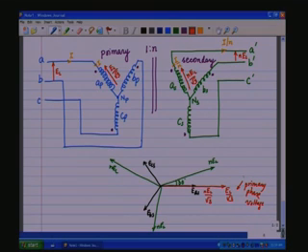And the line voltage is going to lead the phase voltage by 30 degrees. So, therefore, you will have the line voltage EL applied here. This is EAB.